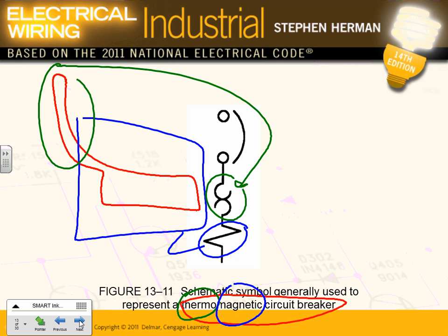Can you guys see it, how they curve? This is the inverse time current characteristic curve that you're going to be drawing with Chad in a second, later on next week. When you see a curve like this, the top is thermal. This little link here is the magnetic. Any comments? That's what the word thermomagnetic means. So this part is for overload. This part here is for ground fault or short circuit.